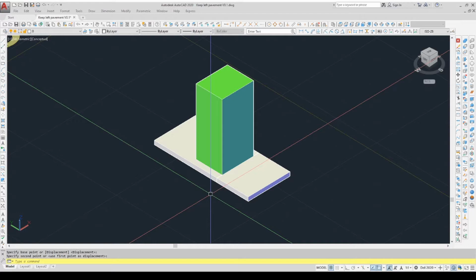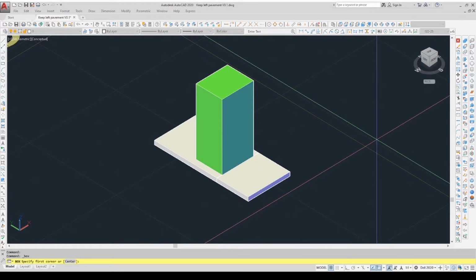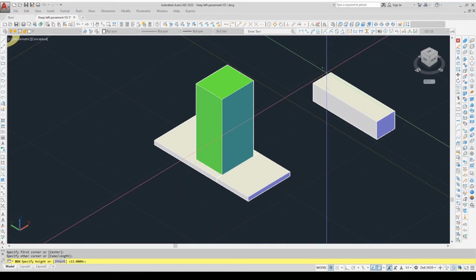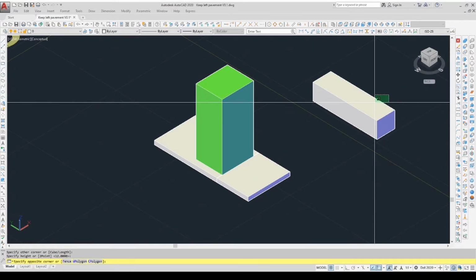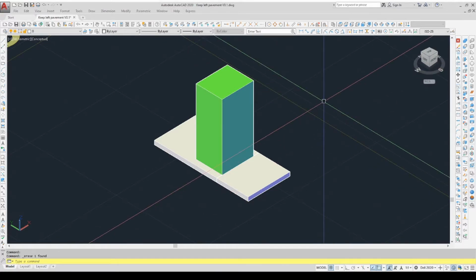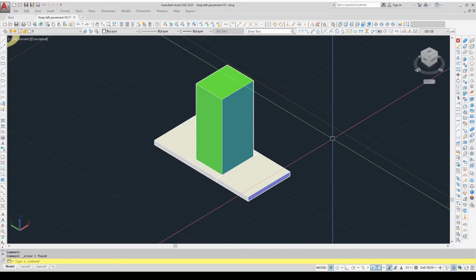Now, a curb stone is a piece of concrete. It's not quite a square oblong shape, it's got a slightly chamfered side. So in CAD, again, there's a couple of ways of doing this. One would be, very quickly I'll demonstrate, to make a block that was about the right size, and I could use a command, that one there, that enables me to form a chamfer on that block, and it would take a chunk out of it. But the easiest way is, I'll just delete that, to draw a cross-sectional outline of the object that you want to do, and then we can extrude it.